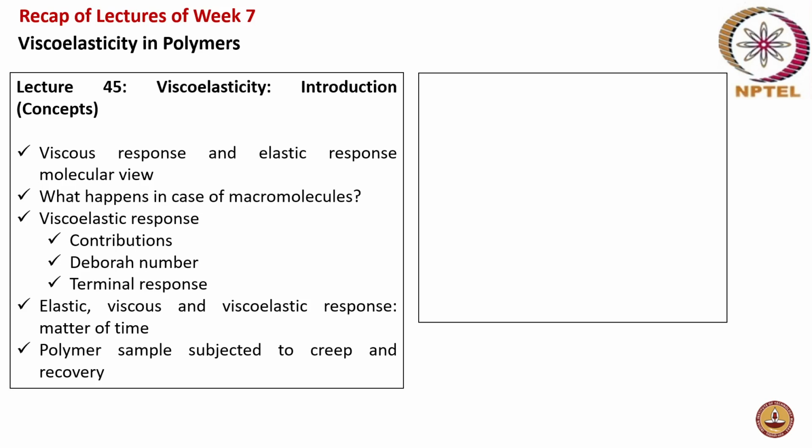And whether a response is elastic, viscous, or viscoelastic is a matter of time. So these things were discussed, and then a polymer sample subjected to creep and recovery. So how does the response change? Basically, this was discussed using an example problem from GATE.